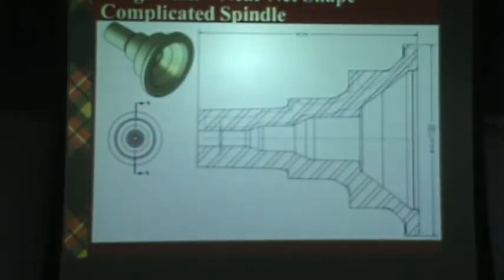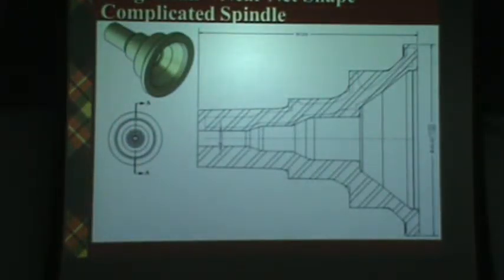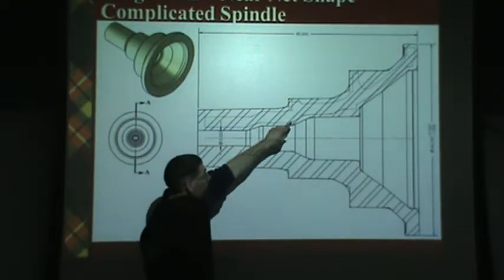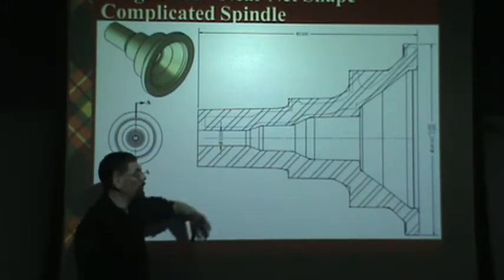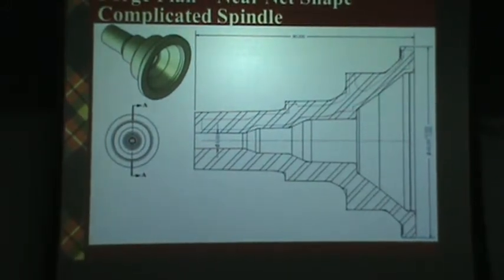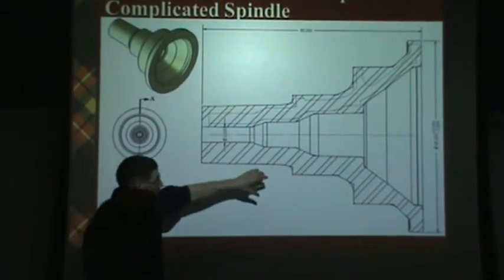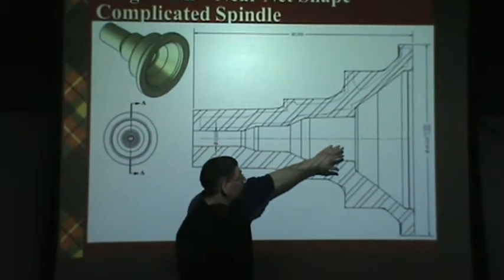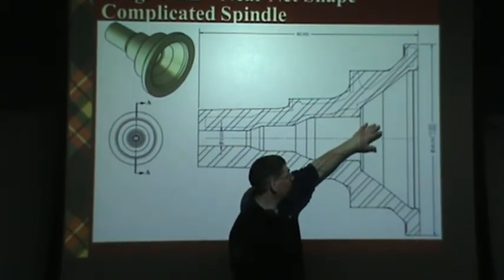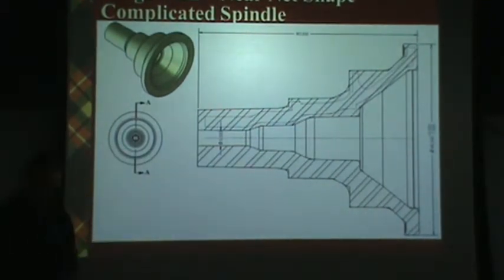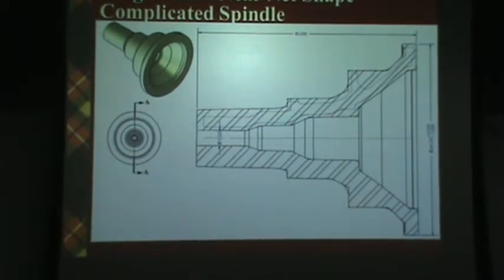Okay. All right, let's talk a little bit about modeling and heat treatment then. Here's an example of a part that I hope you get a chance to see when you come on your tour. You can see here this shadow is what the final profile will look like, and the blockier shape is what we've produced. So you can see that we've got lots of changes in the cross-section in this part. We've got some really thick areas here and very thin areas over here. This is all open, a big counter, what we call a counterform. This is all forward shape. So the potential exists there to have cracking occurring.